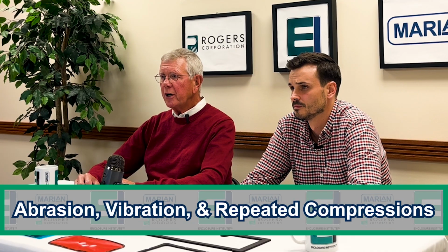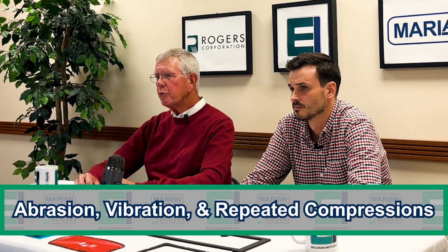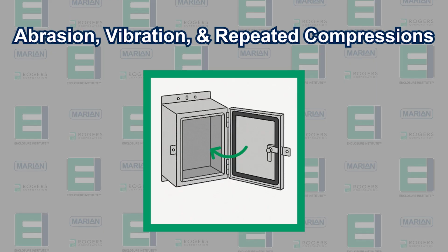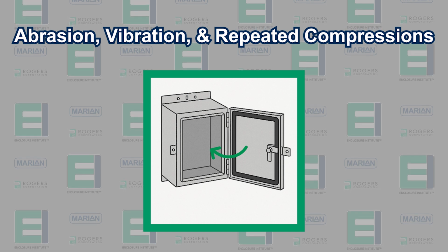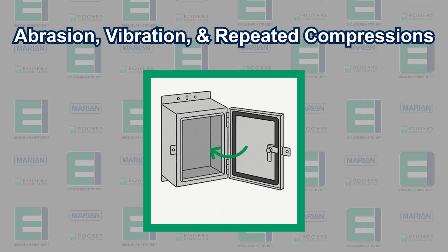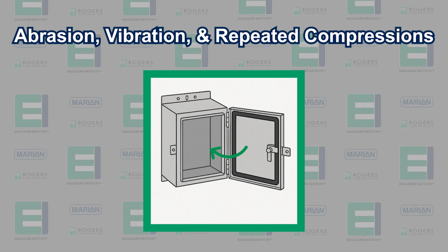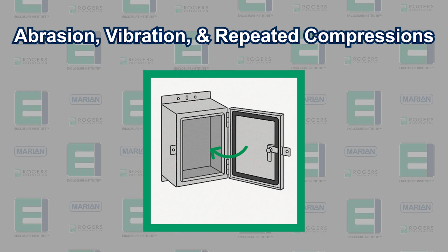Applications that involve abrasion, vibration, and repeated compressions can speed up a gasket failure simply because those conditions are hard on the gasket material. A static seal that's clamped and stable without movement doesn't experience the same stress as a dynamic seal. If the material chosen was a PVC foam, vinyl nitrile blend, or some neoprene and EPDM sponge materials, the physical abuse experienced in these dynamic applications will likely cause failure of the gasket earlier than expected. High-density urethane foam like PORON is more robust and durable and can extend the life of your gasket.